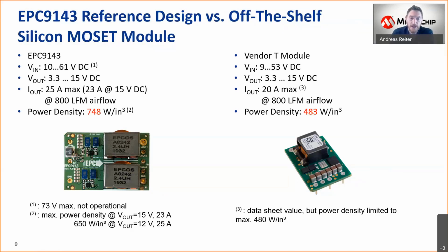And what is most beneficial is there is no body diode, so reverse recovery is basically non-existent. That means we can turn these switches on and off with incredible speed in both directions. And this helps us to squeeze the size of the switch nodes significantly versus a conventional silicon MOSFET design.